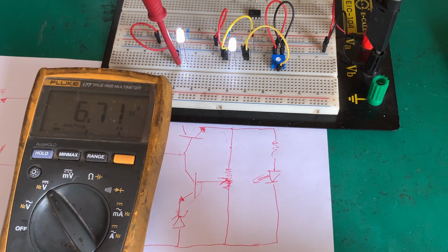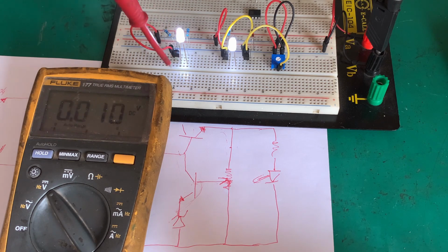7, 8, 1.3 volts down, 9, 10, 11, 12. So we're a little bit down, and that's to be expected, losses on the breadboard and things like that. If I measure the Zener voltage, which will be on the base, we can see our Zener is at 10 volts.